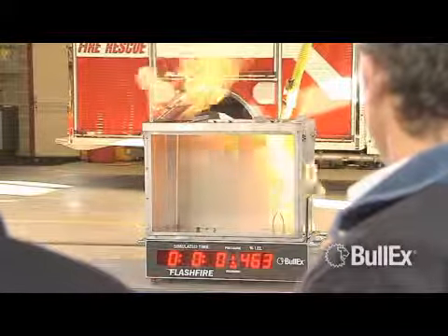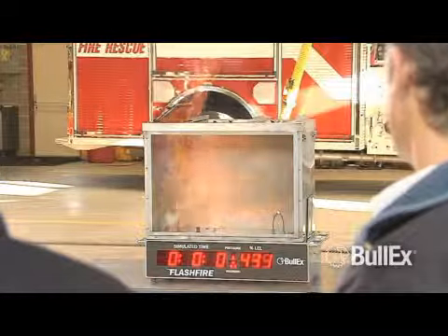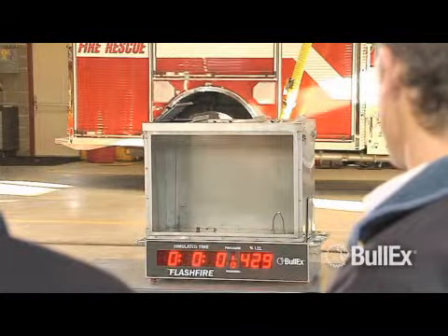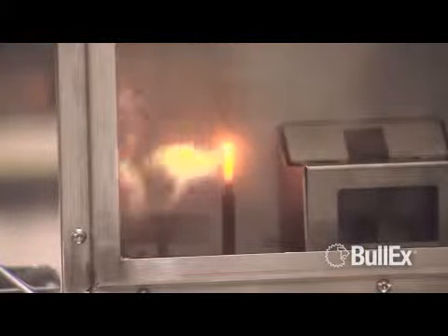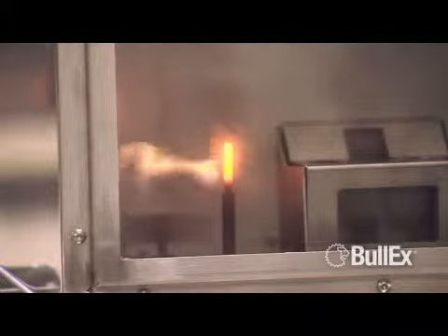The flashovers demonstrate the sudden, rapid deterioration of conditions that occur when combustible materials inside a room reach their auto-ignition temperature. A hot point source is used to simulate the seat of fire, and when the conditions are right, the room suddenly flashes.